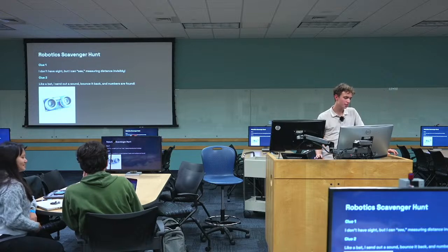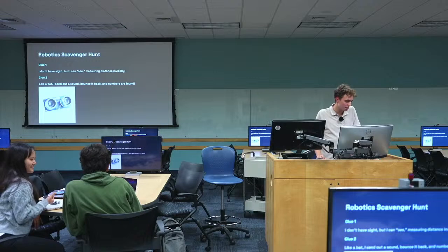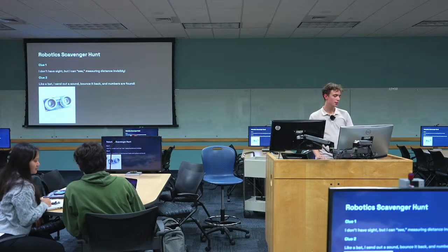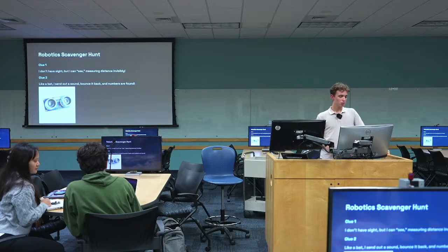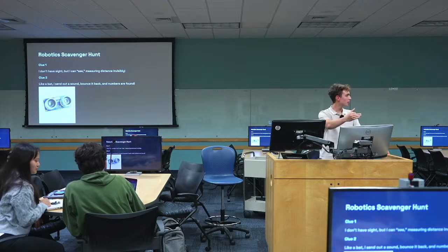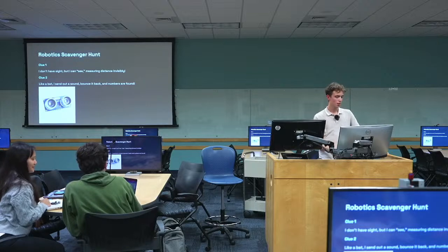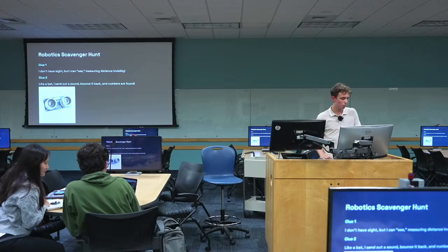This one is definitely very important for robot exploration. It measures distance, right? It's an ultrasonic sensor. You can see there are two circles in the shape of the sensor. One of them is in charge of emitting the sound, and depending on the time it takes to come back, it gives you the distance. This is all done by Arduino internally, and we're going to be using it, so don't worry about the physics.